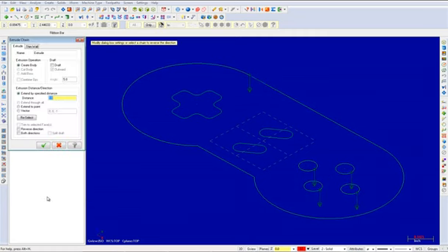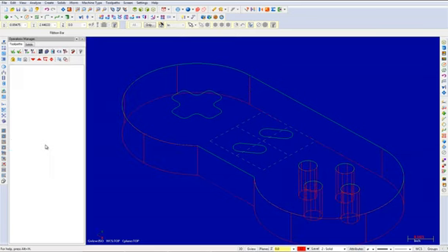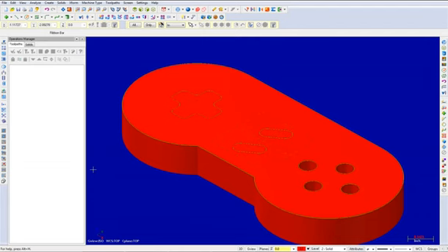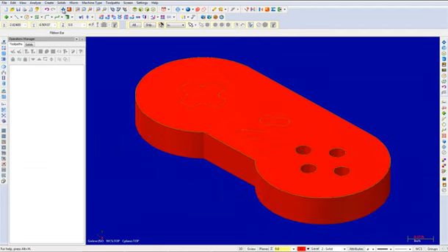In the Extrude Chain dialog box, ensure Create Body is enabled and input a value of 0.5 to extend by specified distance. Once complete, select the OK button to create the solid. Use the icons found in the toolbars to shade or unshade the solid, or press Alt-S on your keyboard. Select the Fit icon to view the geometry. Your part will appear as shown. Unshade the solid.